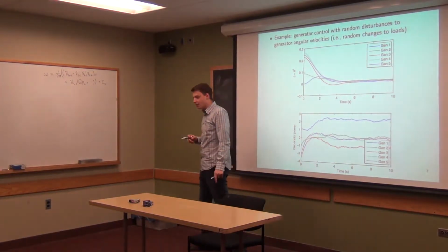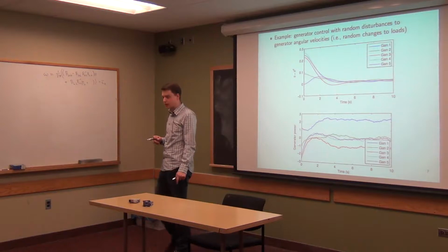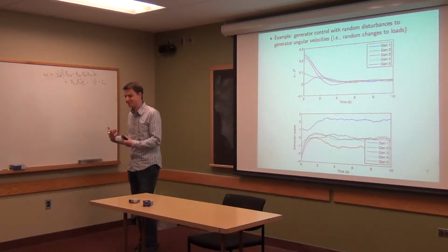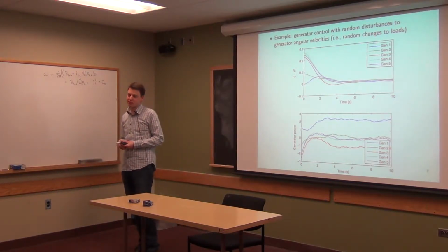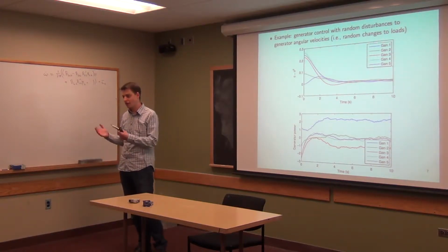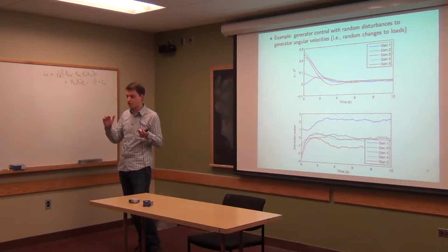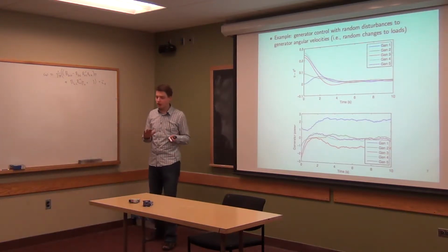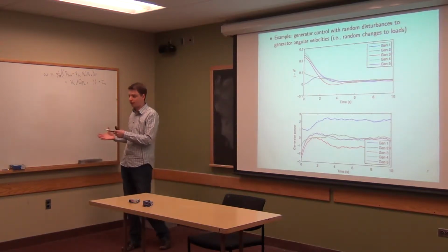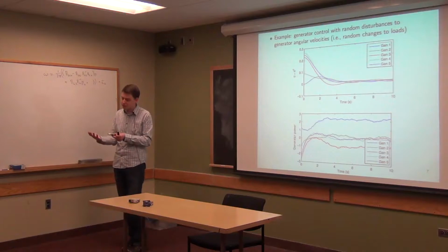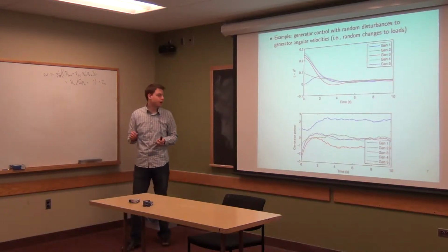You can add constraints that would try to penalize roughness. We talked a little bit, at least in the setting of optimization-based control, about how you could add, for example, constraints on how much you could change control from one time to another. You can do that a little bit with LQR. Again, you have to have just quadratic penalties on it, and you have to actually augment the state a little bit in order to do this. You can do similar things, but it's not trivial there.